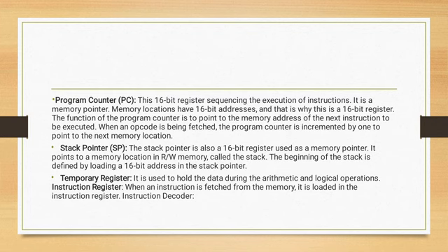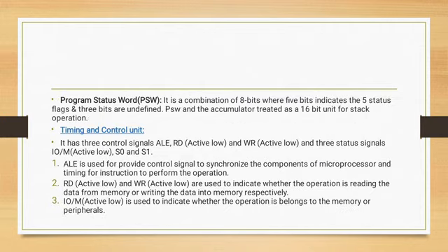Next, the temporary register is used to hold the data during the ALU operations, and the instruction register is basically used for fetching an opcode from a particular memory location, and it is always loaded into the instruction register. So after fetching, the instruction will be decoded and executed by the decoder.